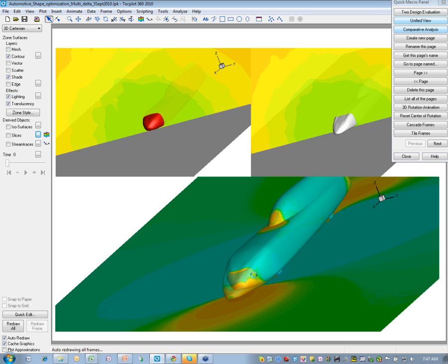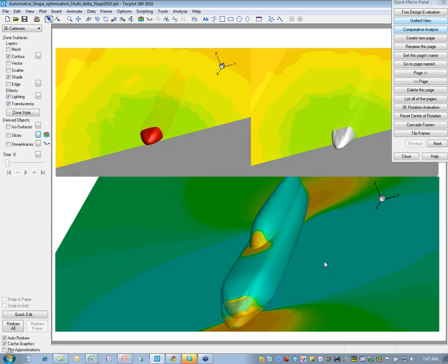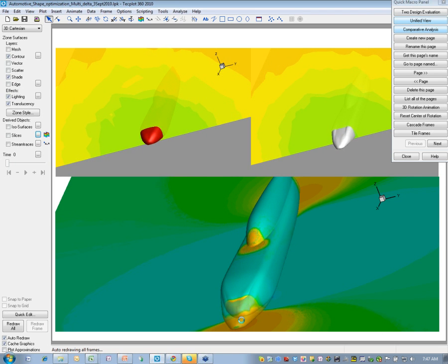You can see that the most significant delta, again, is on the nose cone, which is what was changed. But what's interesting is looking at the actual canopy: the elongated nose actually decreases the pressure on the canopy as well. So if one were to evaluate the lift and drag for these data, you can, in fact, look at what those differences are.